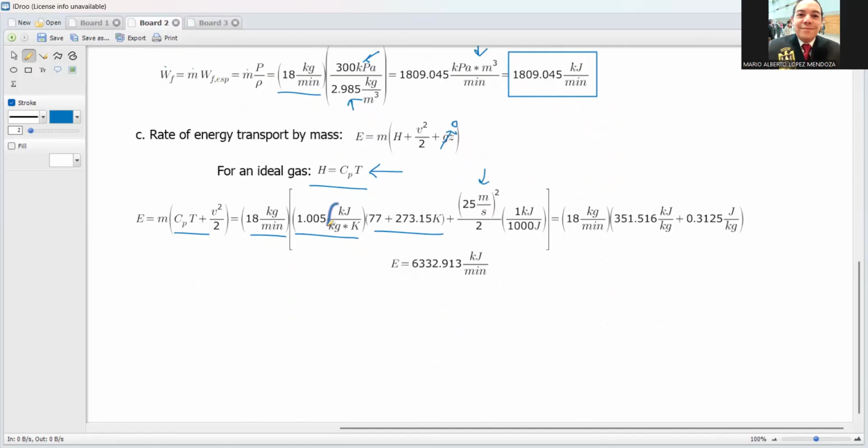The units of this quantity are kilojoules per kilogram, a specific energy. But in this case, the units are square meter per square second. If you do an analysis at the level of fundamental units, you can see that this quantity equals joules per kilogram.